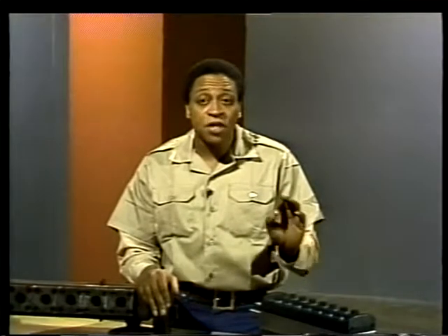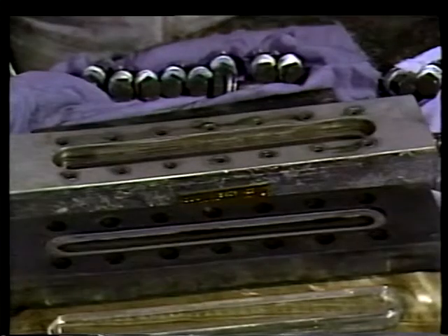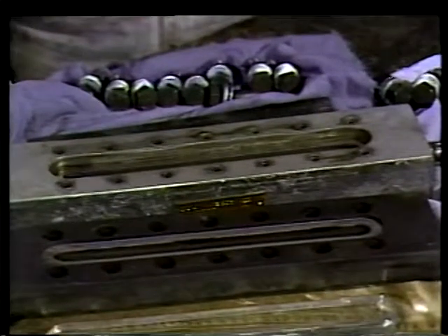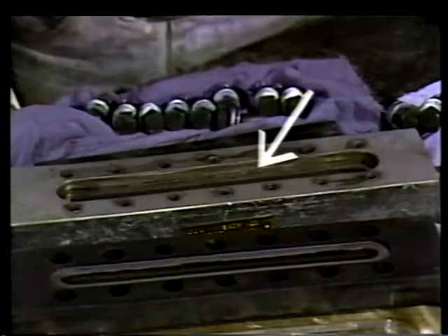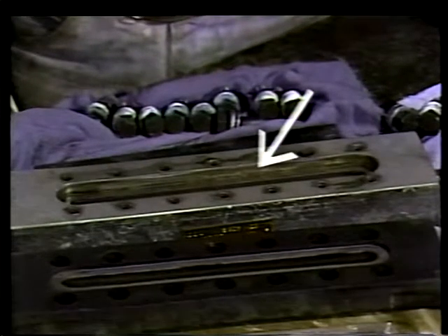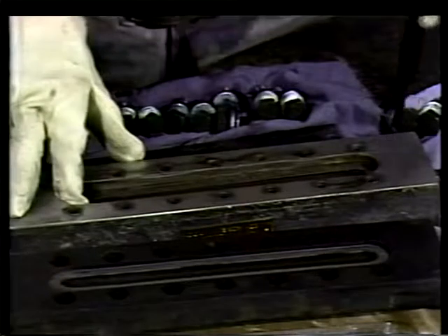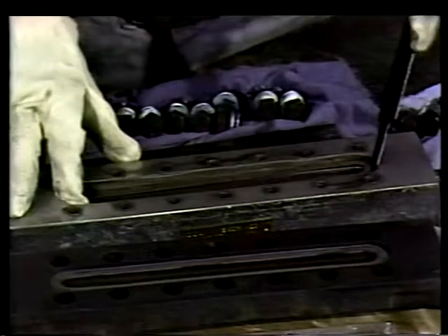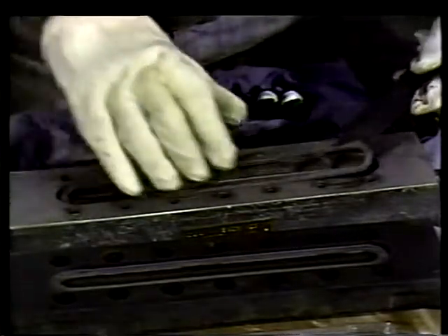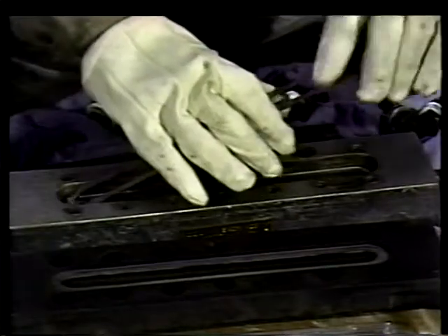The next step in the overhaul is to clean and inspect the parts. Gauge inspection begins with removal of the sealing gasket located in the gauge body. It must be removed very carefully so you don't damage the seating surfaces under the gasket. A small nick or scratch could keep the gauge from sealing properly.